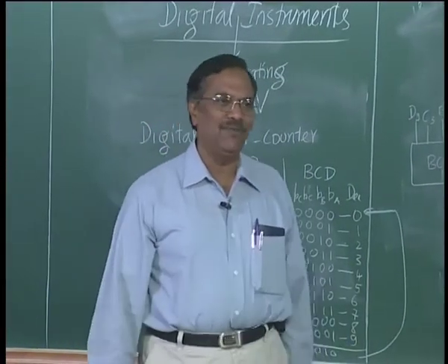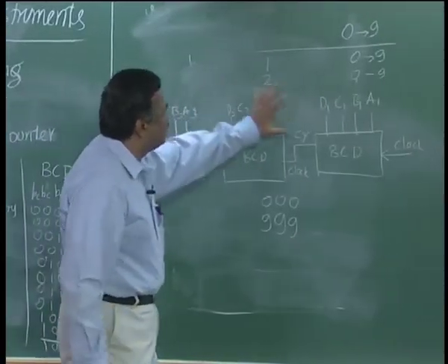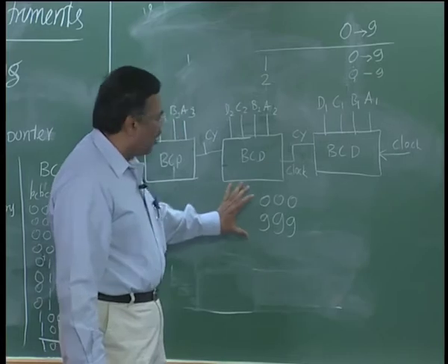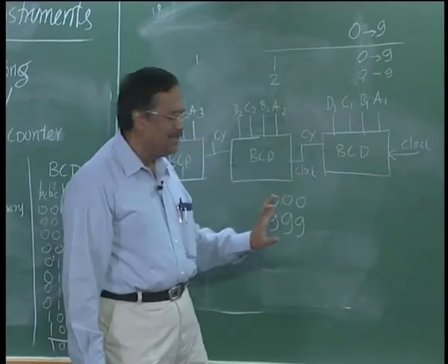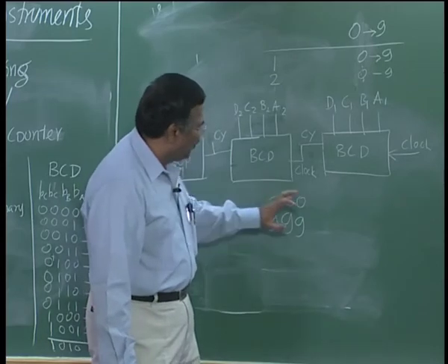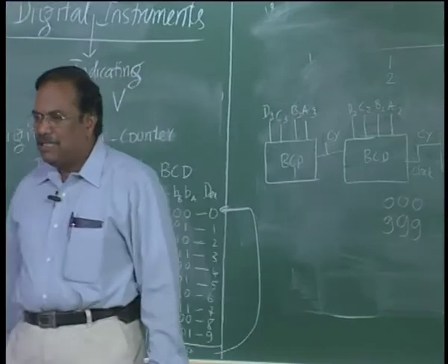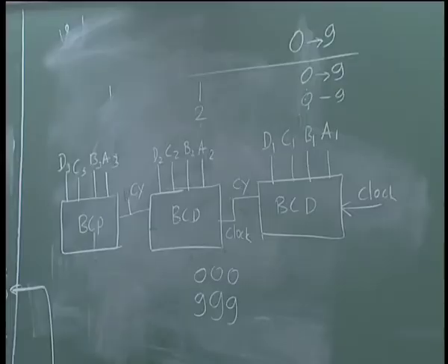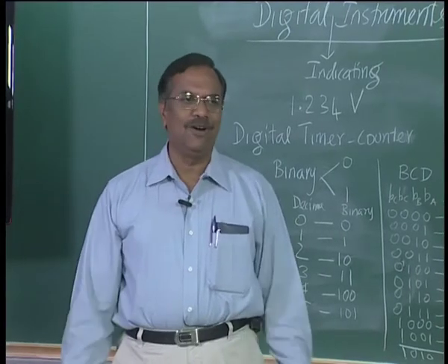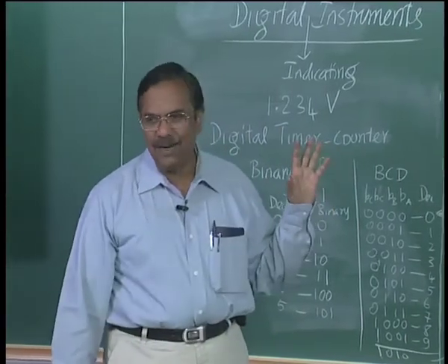It does not matter as far as we are concerned, the outputs, the BCD numbers of these counters will now count the number of clocks fed to the counter from 000 to 999, right. So, if I look at it, there are 999 levels, right, and if I include the 0 level, I call this a 1000 level counter, right, or simply a 3-digit counter.